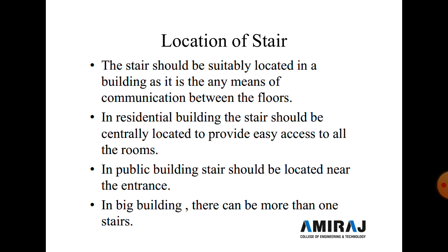Now we start with the location of the stair. The stair should be suitably located in a building, as it is the means of communication between the floors. Generally a stair is located at the corner side, at a place where it is easily seen from all points. In a residential building, the stairs should be centrally located to provide easy access to all rooms.